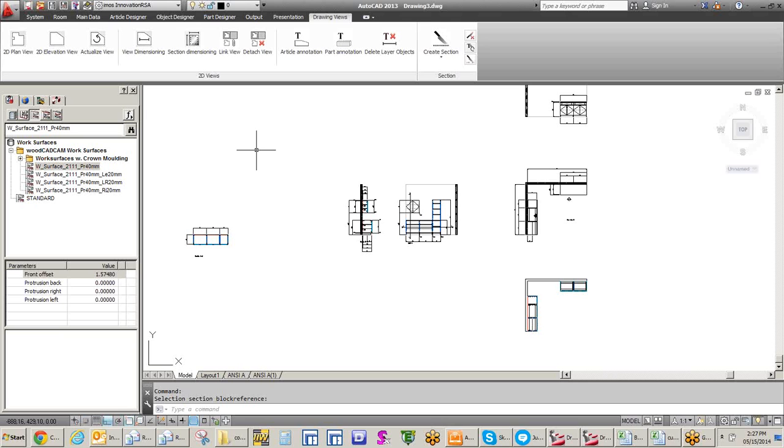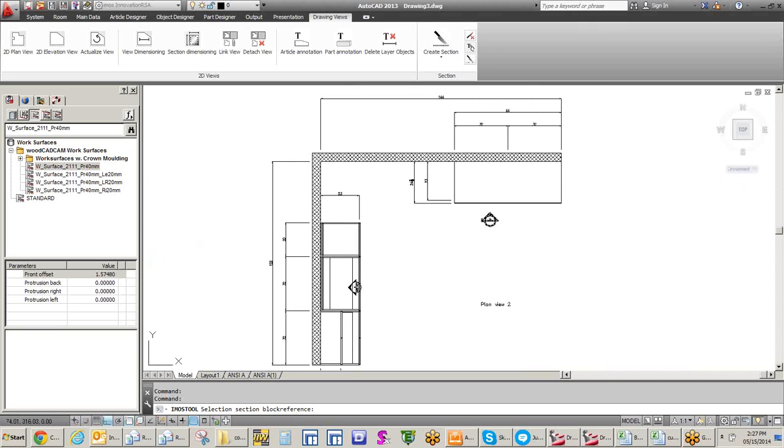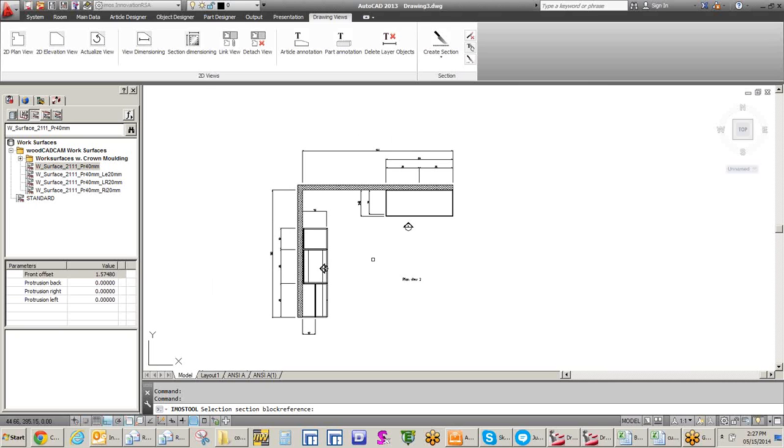And then, do I select the one elevation in 2D or in 3D? You select it in 2D from the plan, the 2D plan view. Okay. Because that's where you want your elevation markers to be, relative to that 2D drawing. Okay, so I'm hitting the 2D elevation view. Yep. And I'm clicking on the plan view, just on any one of the cabinets in that elevation? Yeah. Okay, and would it be a left click or a right click?